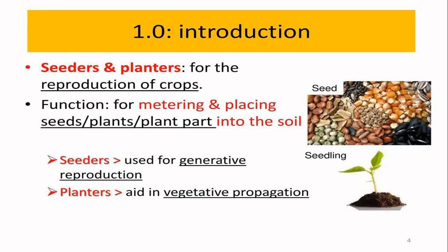Who will make the hole on the seeder? Someone does holes? No. The seeder has in front one device called a furrow opener. Furrow means deep hole. It will dig, right? Sometimes a wheel is there, sometimes a very long metal rope is there. It goes inside the soil and makes a hole. So what is the function of the seeder? Put the seed in the proper hole. In front one wheel is there. It makes the hole depending on the wheel diameter.